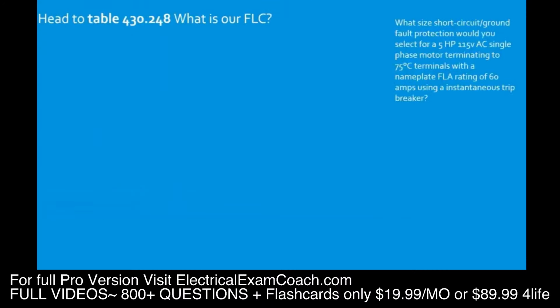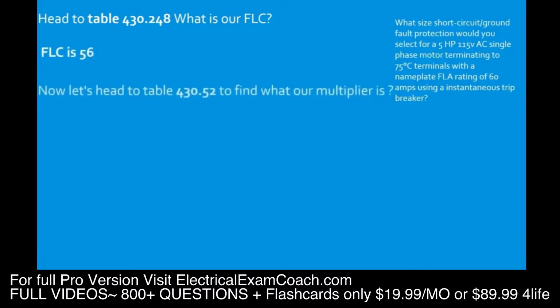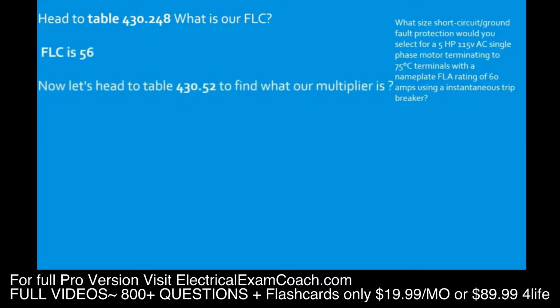We head to table 430.248. What is our FLC? Starting on the left-hand side with our horsepower, coming across to our voltage, we're going to find that the FLC is 56 amps. Now we head to table 430.52 and find our multiplier, starting on the left-hand side, finding single phase, then coming across to the type of device. In this case, we're going to find that our multiplier is 800%.